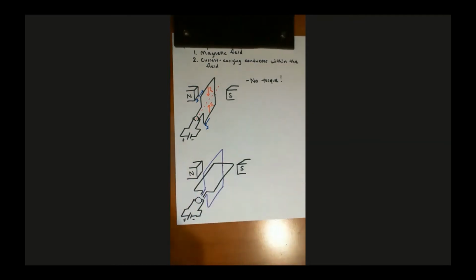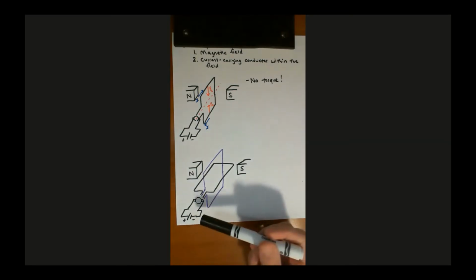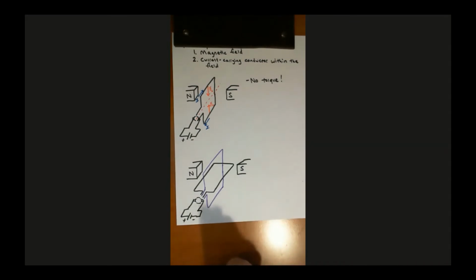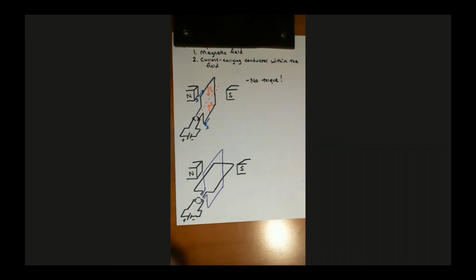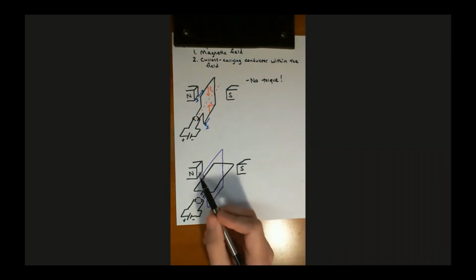Okay, so now the voltage is only going to be applied to one coil at a time, and it's always going to be applied to the coil that can produce torque. So in this, the way I've drawn it right now, and I know I haven't drawn these connections because it just gets tough to draw, but what we would have right now is that the applied voltage would be applied to the horizontal coil, which is the black coil, and it would not be applied to the purple coil.